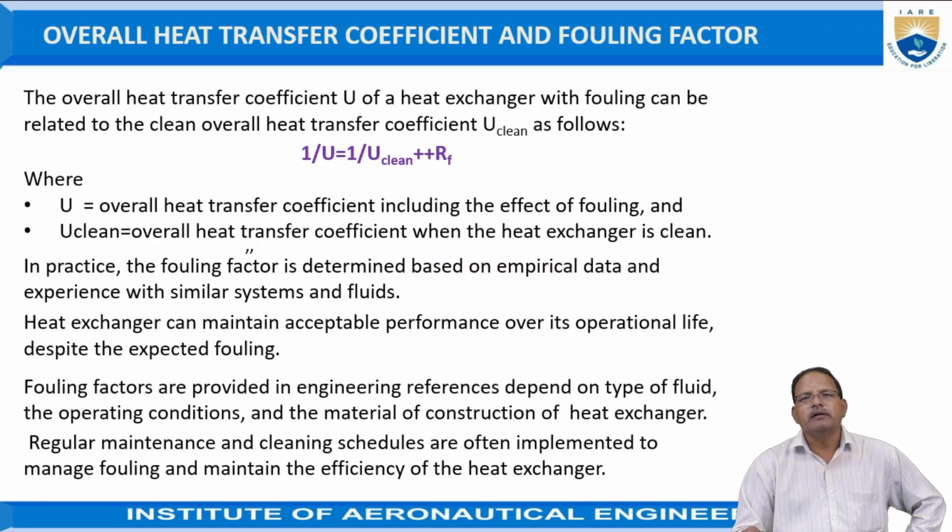The heat exchanger can maintain acceptable performance over its operational life despite the expected fouling. The fouling factors are provided in engineering references depending on the type of fluid, operating conditions, or material of construction of the heat exchangers. This value changes depending on the type of fluid flowing inside. Regular maintenance and cleaning schedules are often implemented to manage fouling so that the efficiency of the exchanger can increase or be maintained almost uniform.